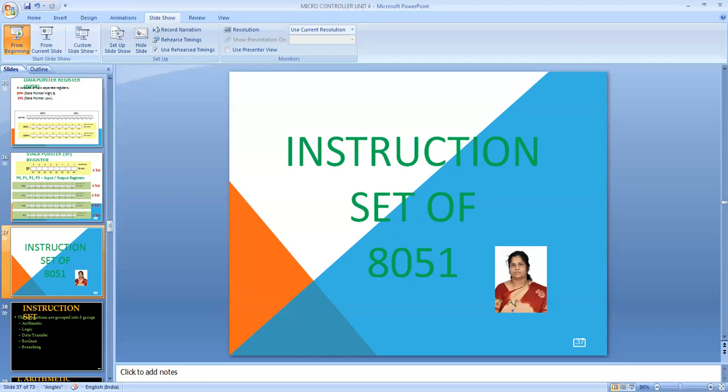This is an example for the multiplication of numbers. The command is MUL AB. Here we are giving the data A equal to 7 and B equal to 2. What is the value? 7 into 2, 14 we have to get. Now the data in hexadecimal fashion will have 0 to 9. After that, 10, 11, 12, 13 will not be used; instead, it starts with the values A, B, C, D, E, F. So 14 we have to write as E. That is for the number 14. Similarly, division of numbers also will be performed.